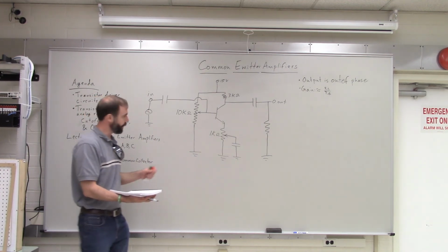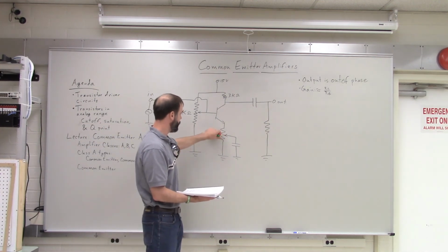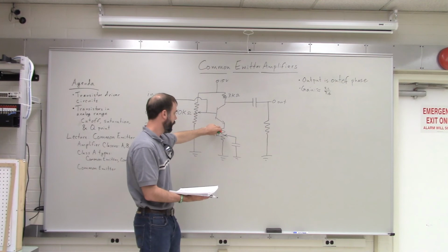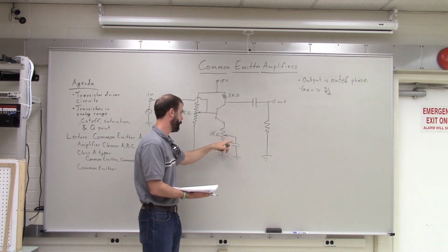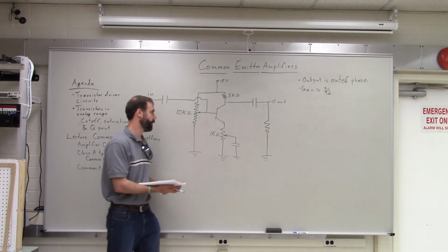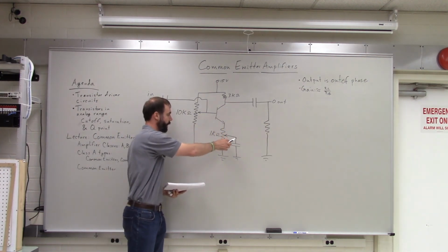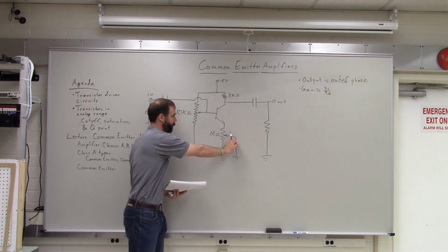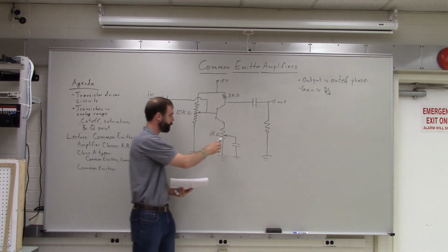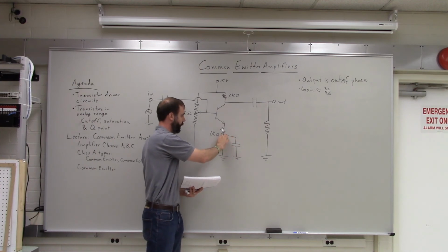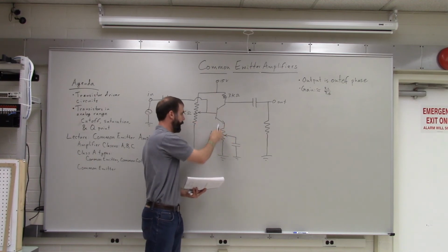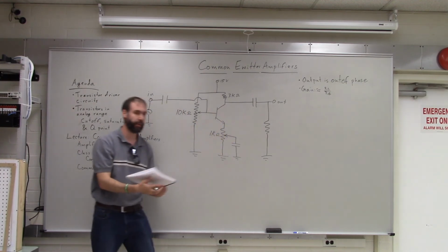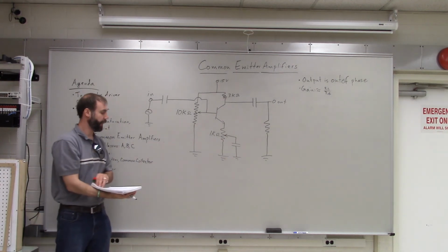And then what you're going to do is change this potentiometer around. You're going to use the dial on this potentiometer to change the place where this capacitor is connected. So basically, changing this around is going to put this in parallel with more or less of the resistor. So it'll change the resistance down here, and that will change the gain of the circuit again.